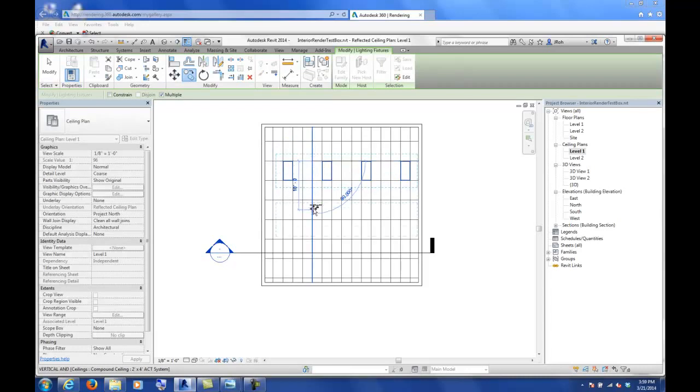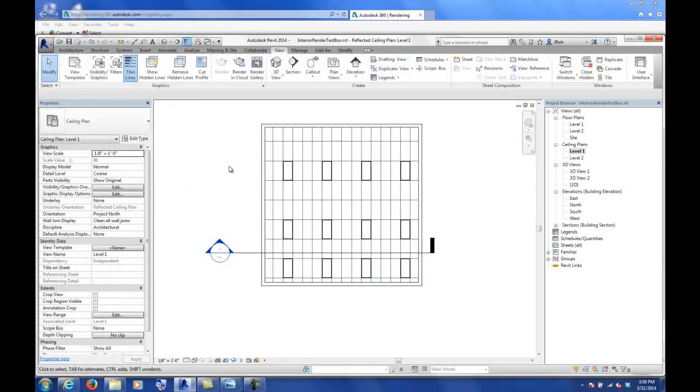So next time you're kind of walking down a hallway or in another room, take a look up and see how many lights there are in a room. And that's generally what you're going to need to produce when you're trying to make your interior rendering. So keep in mind that before you just get a nice interior shot, you need to spend a little bit of time thinking about the lighting design and throwing in lights, because that's what's going to show up.